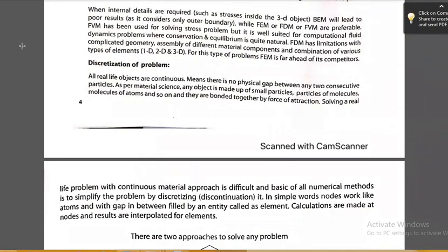The object can move in x, it can move in y, it can move in z. Similarly, this object in space will rotate about x, similarly about y, and similarly about z. That means there are 6 parameters that the object will have. So that's why we can say that an object in space has 6 degrees of freedom. Freedom means it can rotate in all three rotations, or translate linearly in all three directions. That's why this object has 6 degrees of freedom in space.